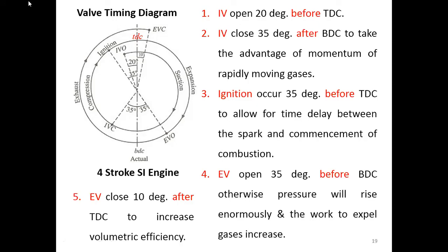So you can see that we have more time for the fresh air, or the air-fuel mixture, to go in, because we want to take advantage of the momentum from the rapidly moving gases. Because the gas keeps moving, it has momentum. So we make use of that momentum to induce more of the gas to flow in.